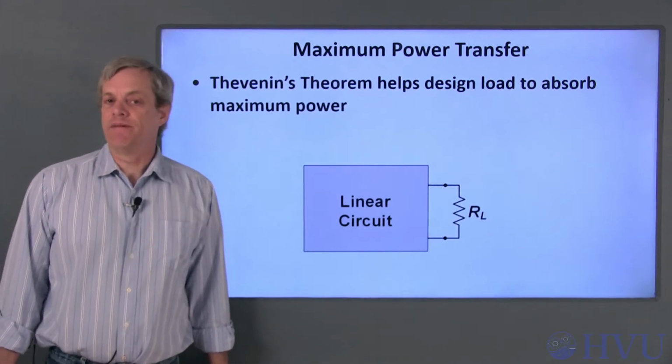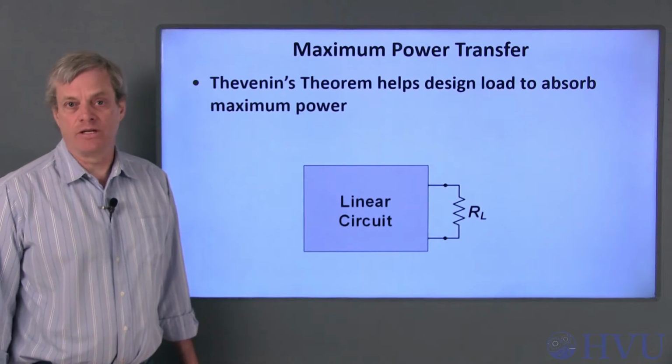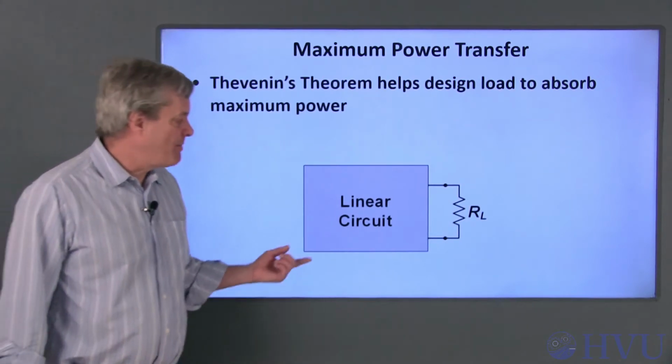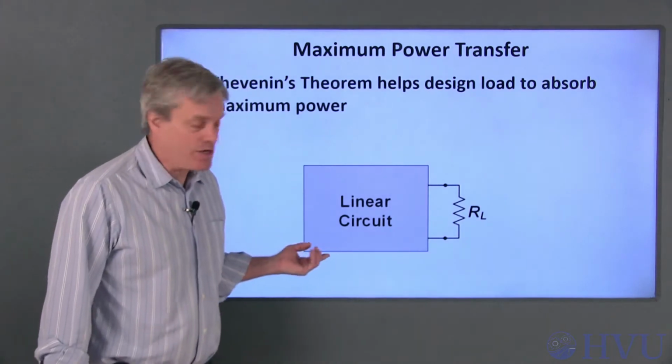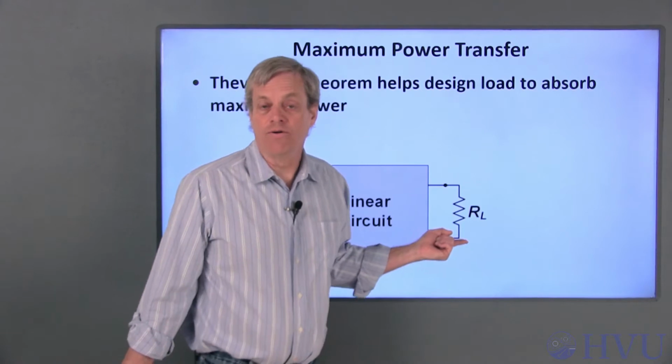Before deriving the maximum power theorem, I'll give a quick overview of the problem and the primary result. The general idea is that we want to transfer the maximum amount of power from some circuit to a load. I'll use a resistance, RL, as my load.